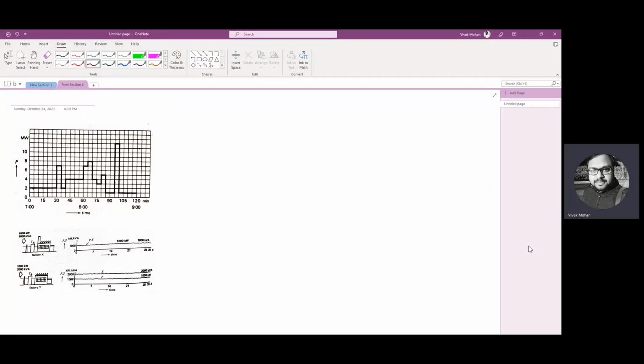Okay, so we have seen what a demand meter is and how the demand meter measures the maximum demand and demand for a month. So we'll use an example to demonstrate the use of the demand meter, or how the demand meter calculates the electricity bill. So please see this figure.